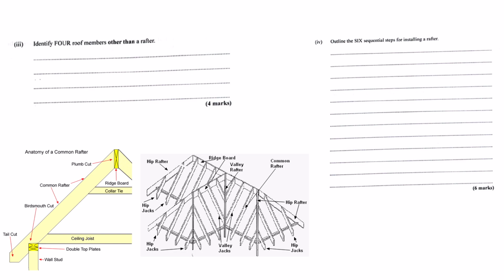It's another horizontal beam, but it runs underneath the rafters, supporting them somewhere along their length, usually mid-span. So it stops them sagging in the middle. Exactly. It adds extra strength, prevents bowing, especially if you've got heavy tiles or snow load. Got it. Mid-support. What's number 3?